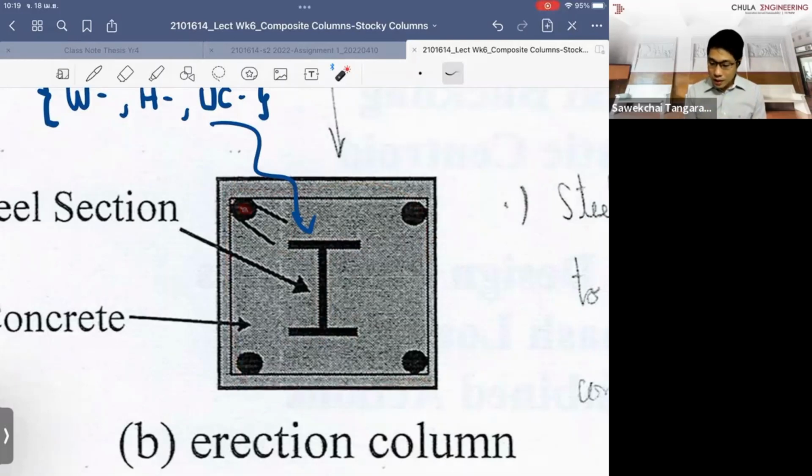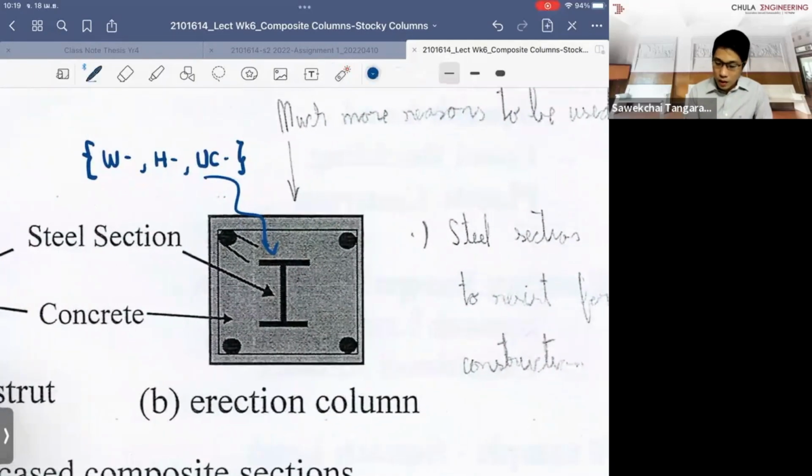One other thing is that when you have the reinforcing bars here, more likely we provide some partial confinement to the concrete. It doesn't provide full confinement to the concrete. So that's why, when we look at the concrete strength, we use 0.85 f'c, which is similar to what you did.